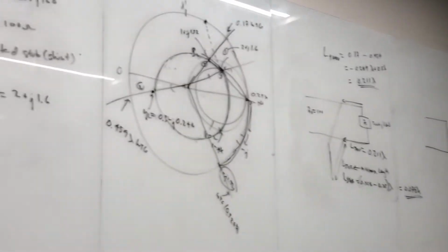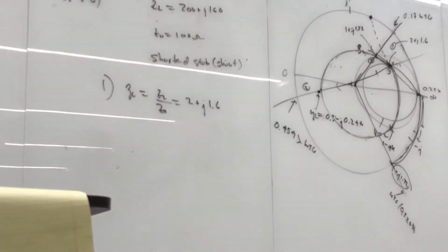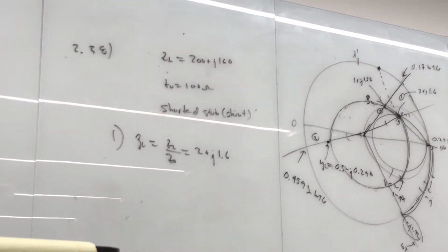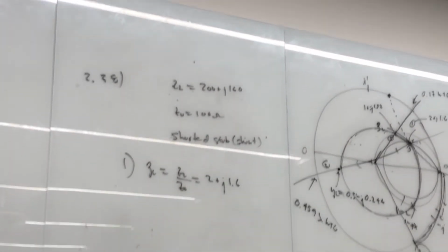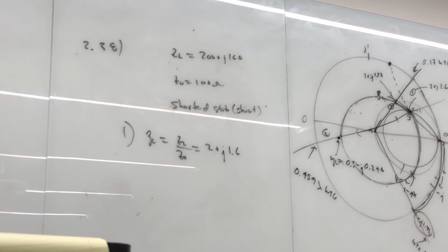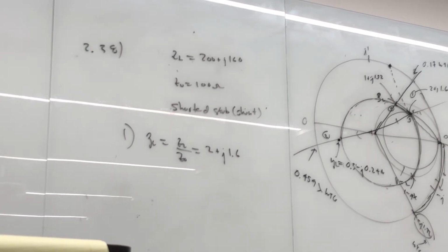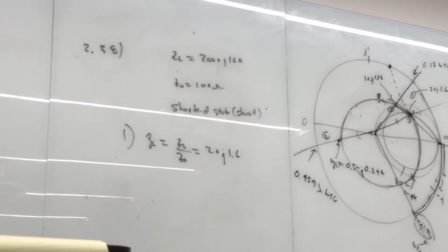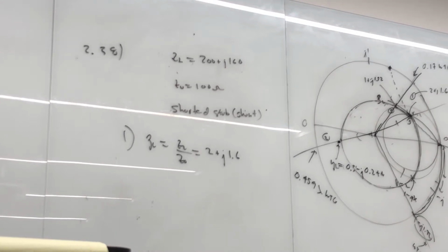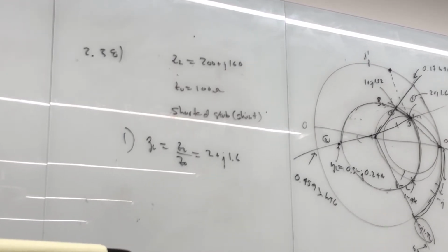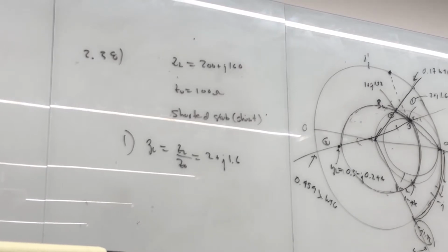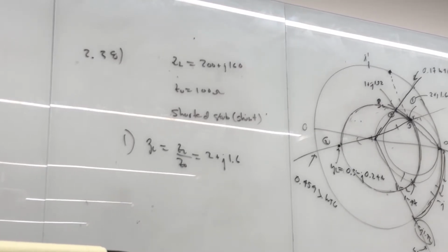We're not looking for where it intersects. No, this is on the edge, because this is the impedance, there's no real part. When you take ZL as 0, 1 over that is infinity, and that's where you start, but it's j right here. So if I'm going down there, all these are j something, there's no real part. If there was a real part, it would be in here. So you're going right on the edge, 1.32, about there.